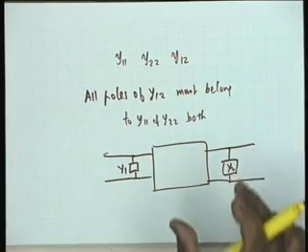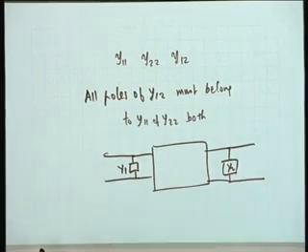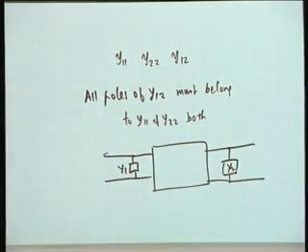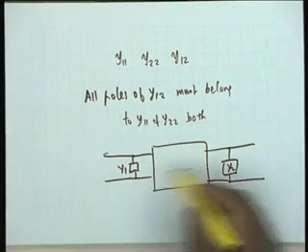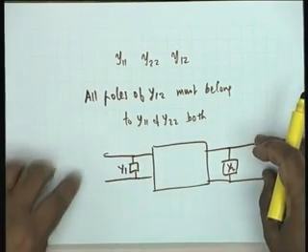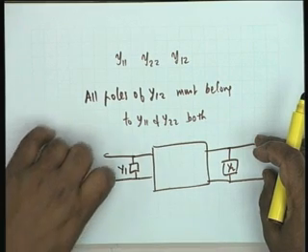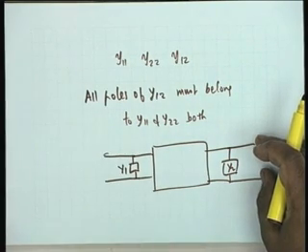It is exactly the dual of the previous case. In the previous case, we had used two impedances in series. Now there are two admittances in parallel. Y1 does not affect y22. Why not? Because in measuring y22 you have to short this. So y1 goes out of the picture.